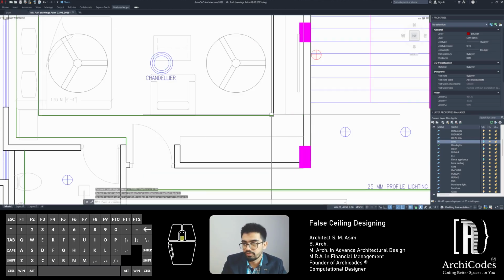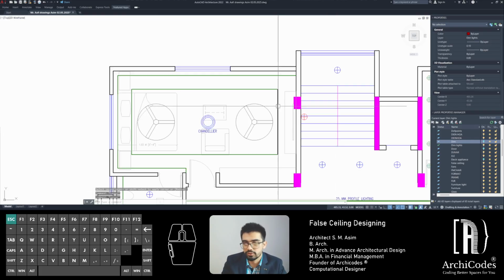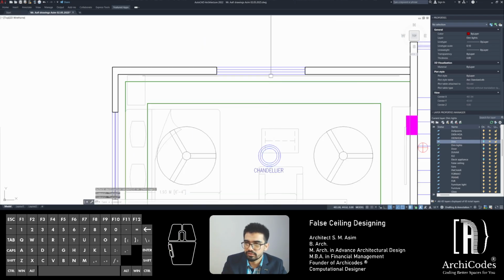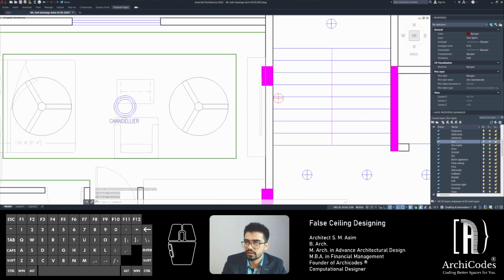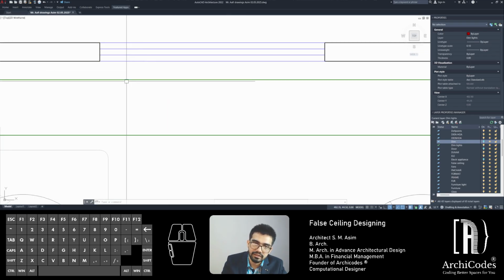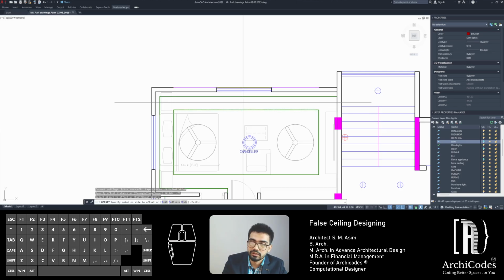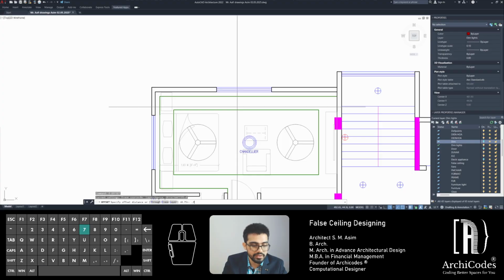F, and even if they don't do anything, it'll still look good because it is 2 feet, which is the same distance from wall to the false ceiling. In case they do something, then the distance of this wall to the false ceiling is the same as this part to this part. So I'm simply going to offset half of 1.5, which is 0.75. Oops. Offset 0.75.